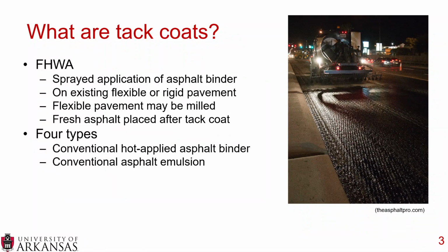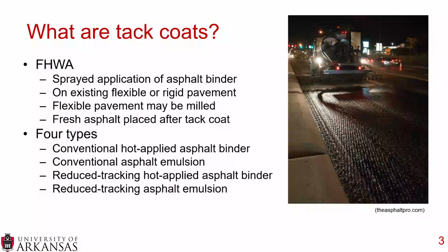And there are 4 types of tack coats. There are conventional hot applied asphalt binder, conventional asphalt emulsion, reduced tracking hot applied asphalt binder, and reduced tracking asphalt emulsion. And at the end of the day, what a tack coat does is it bonds the asphalt layers together.